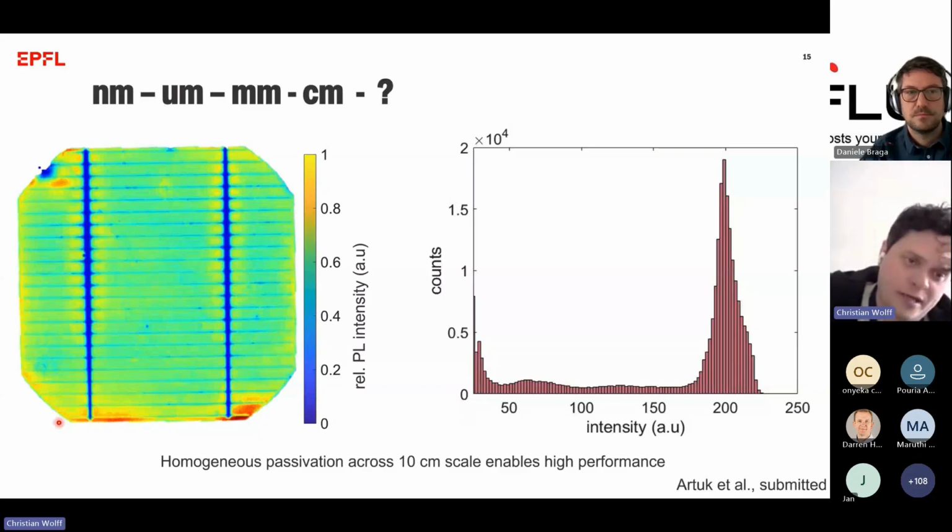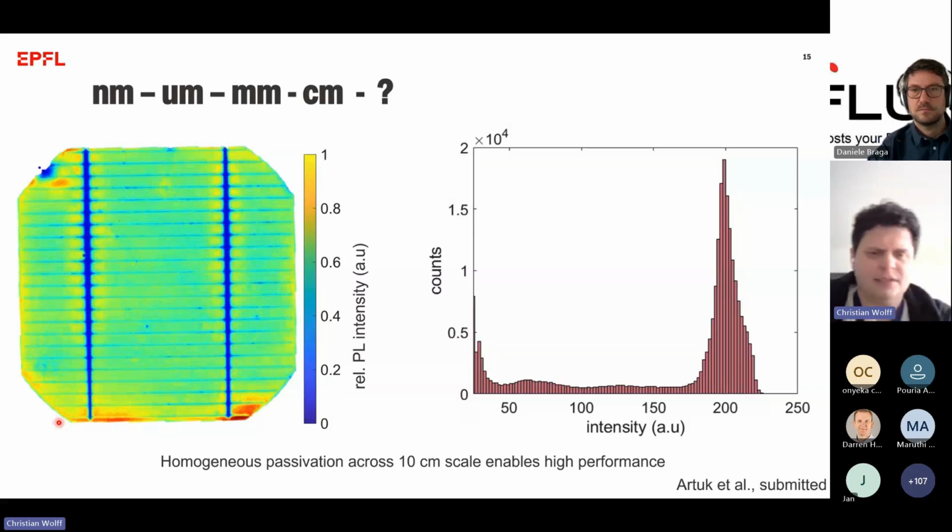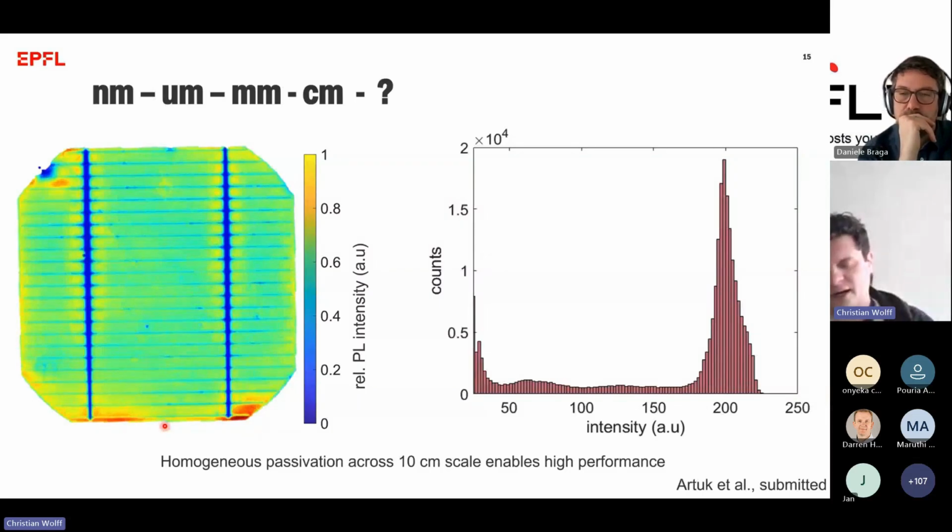I would have to go back and take a look at the setup. It could be that it's not perfectly flat, so it's a little bit tilted, and then the lower part is a little bit closer to the camera, so receiving a little bit more light or just having favorable emission into the camera system. But otherwise, I agree, it's a little bit surprising, right? Near the edges, where you may or may not touch your wafer, you typically get lower signal and not higher signal.